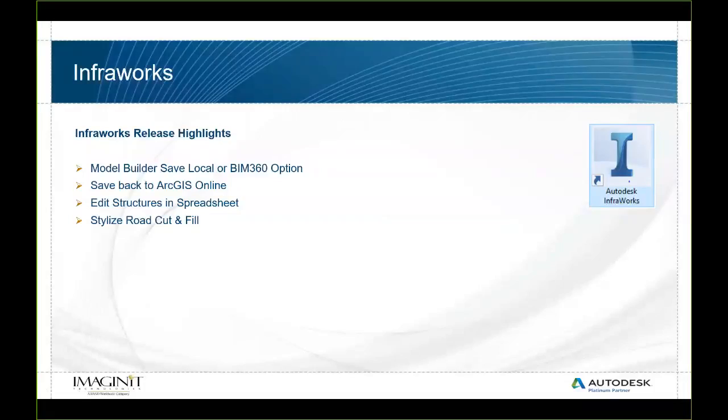The other two new or nice enhancements in Infraworks start with the ability to edit structures in spreadsheets. The structures we're talking about here are bridge structures. So if you've got bridges that you're modeling with the piles and foundations and things, you can export all of that data out to an Excel file, make changes, and then update from the changes.